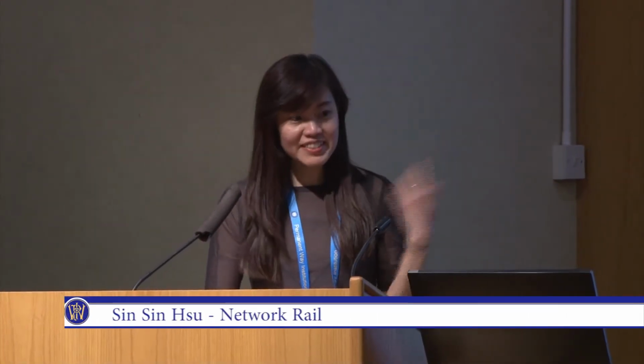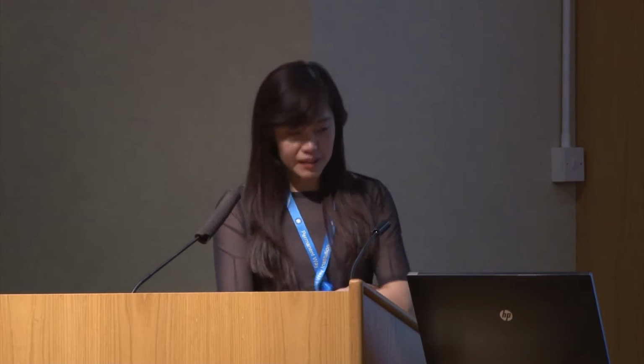Today I'm presenting some modeling work that I've done to improve the S&C performance and reliability within Network Rail. What I've found after joining the S&C team 2 years ago, actually it's 2 years ago today, is that we may design a component or layout that we think is perfect, but if it excites the resonance frequency of the train or causes unnecessarily large forces, then it's not a good design.